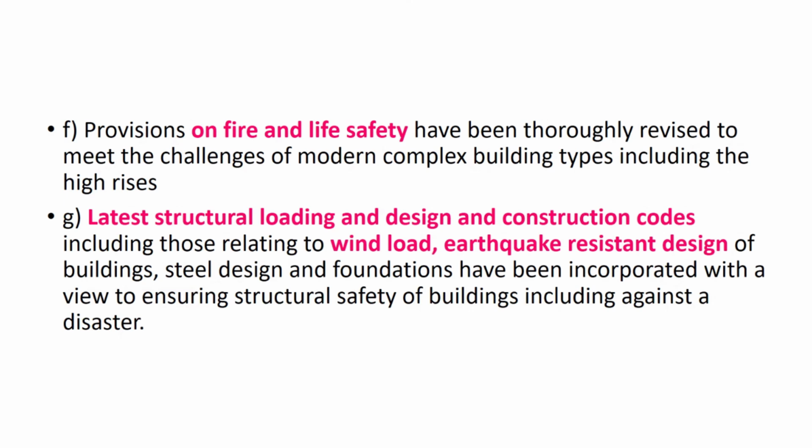Yes, what you are saying is that I have made a provision in the structural element itself that a 4 inch diameter pipe will be taken through in this particular case. That is required to be pre-planned. What you are saying is that at the time of planning itself, it should be catered where the pipe should go, where the sanitary pipe should go, and all these things. That should be designed. That's why I was just telling you that these things are required to be frozen in advance.